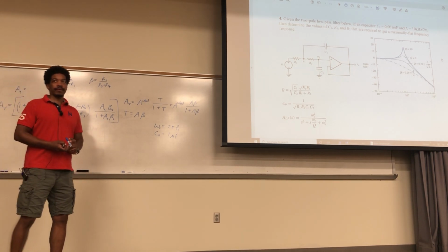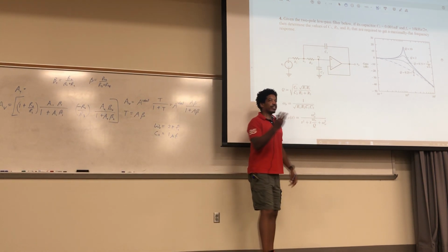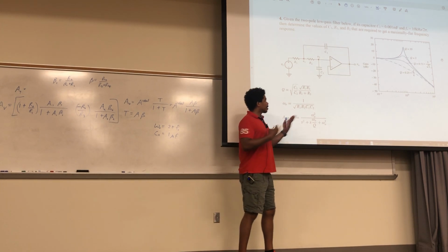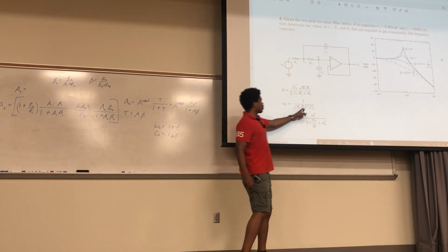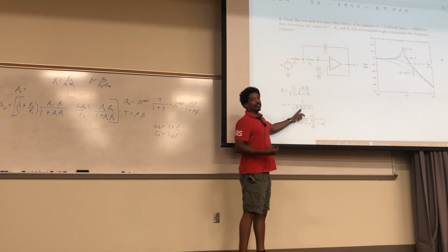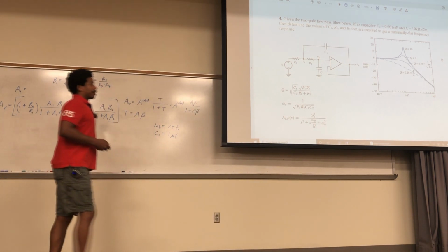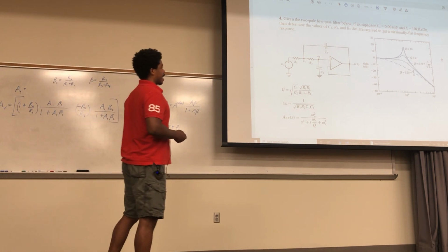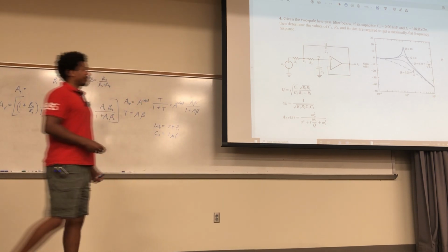You guys see that? There's nothing wrong with doing that because you have 3 parameters, and you're free to choose. So as a designer, you just put a constraint on one, or you could say, well, I have an R2 laying around in my resistor box, and it's so many ohms, and that'll be your constraint. And then your R1 is then unknown or something. Any of those will be fine. So 2 equations, 2 unknowns. That's actually enough to solve this whole problem. Okay? That's all you do.